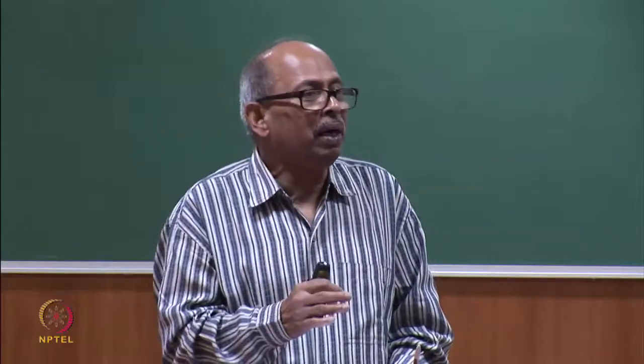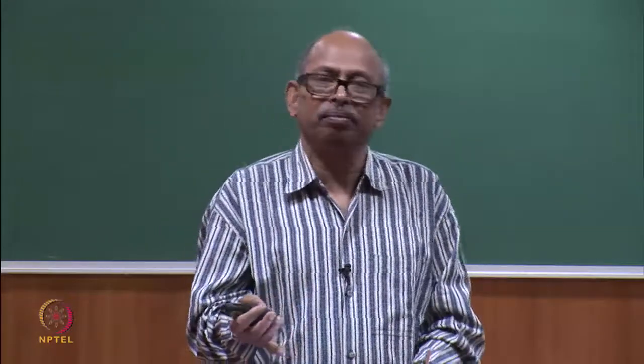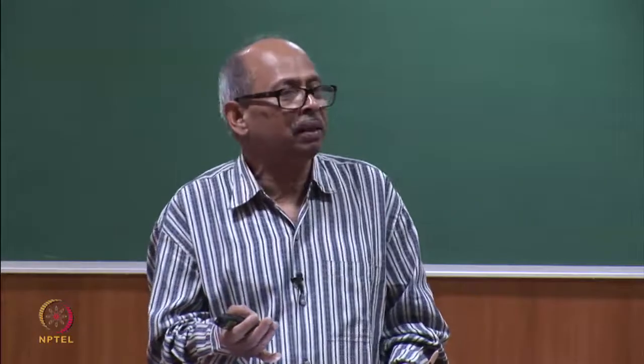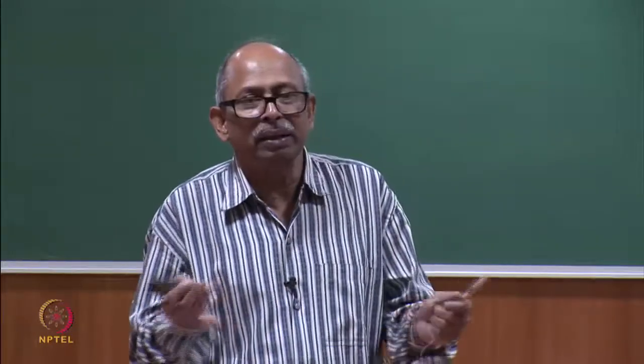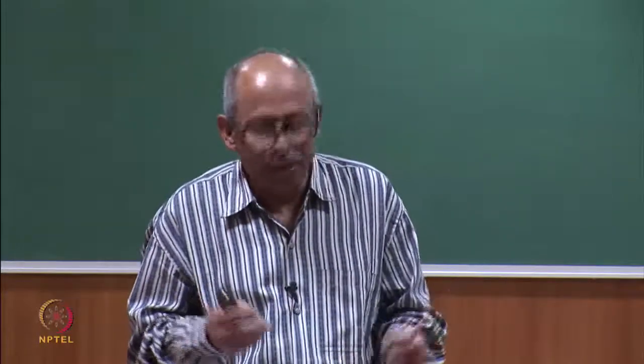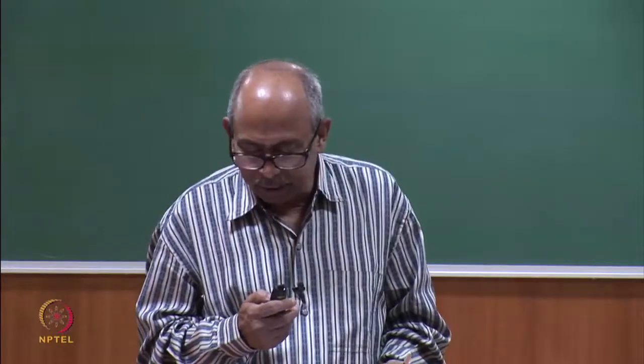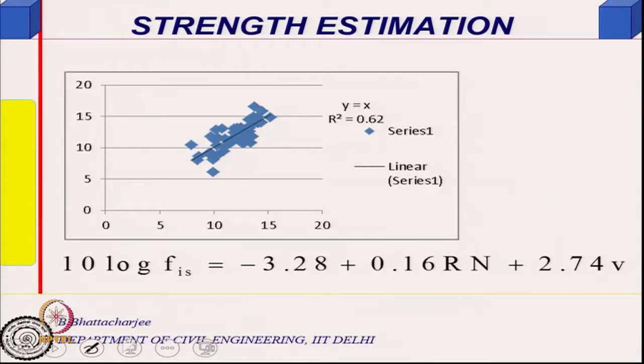Then we used rebound number and ultrasound together, and multiple linear regression using Excel. LINEST is the function available in Excel. So it is not a problem these days to do all this, and it gives us better results, nearly 80% of the results.